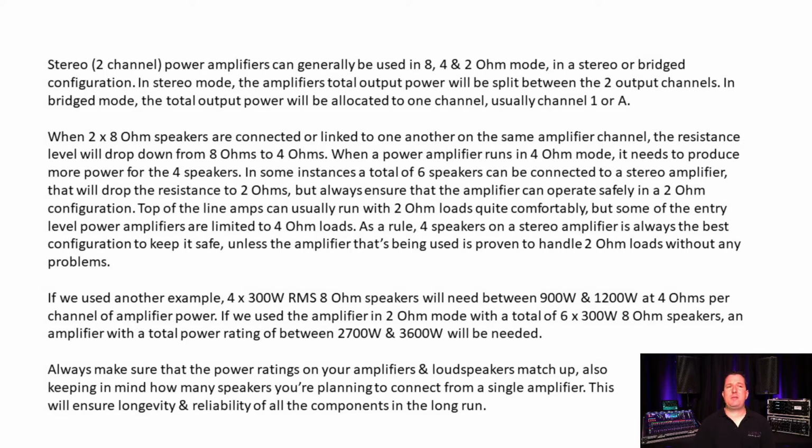Always make sure that the power ratings on your amplifiers and loudspeakers match up, also keeping in mind how many speakers you're planning to connect from a single amplifier. This will ensure longevity and reliability of all the components in the long run.